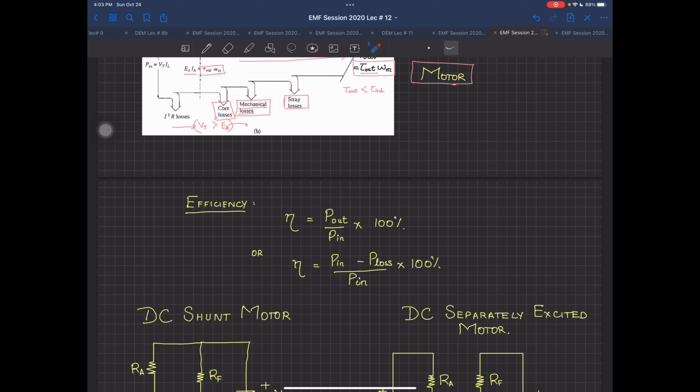They are 4-pole machines. I asked you in the last lectures how many poles there are, and I don't know how many of you tried to find out. Our lab machines are all 4-pole machines with 1500 RPM as the rated motor speed and 1800 RPM as the rated generator speed.